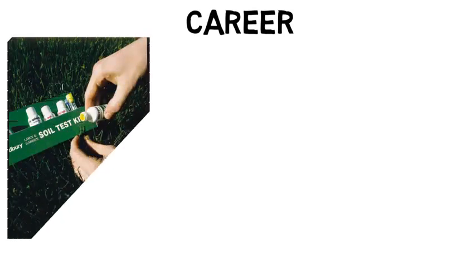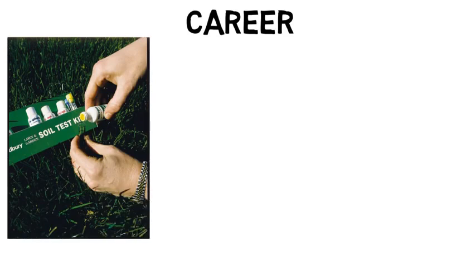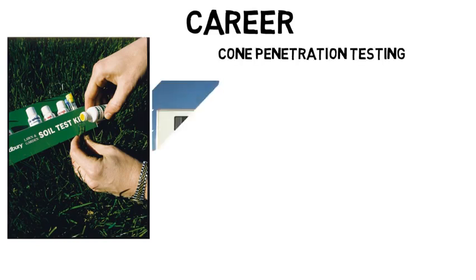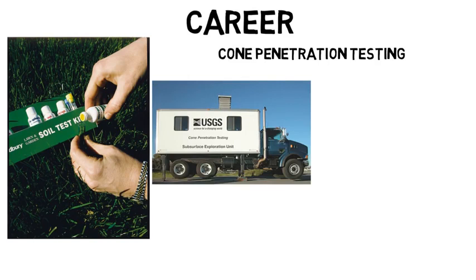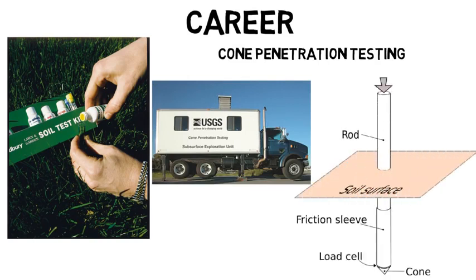You might be the person who goes out to the field where a structure is going to be built and collects soil samples all around the area for testing. Or you could do testing at the field. One of the most used tests right now in this field is cone penetration testing, where a large truck goes out to the field which has all this equipment on it, and a cone is pushed into the soil, and the pressure will be monitored by a computer on the truck as it moves through the soil into the earth.